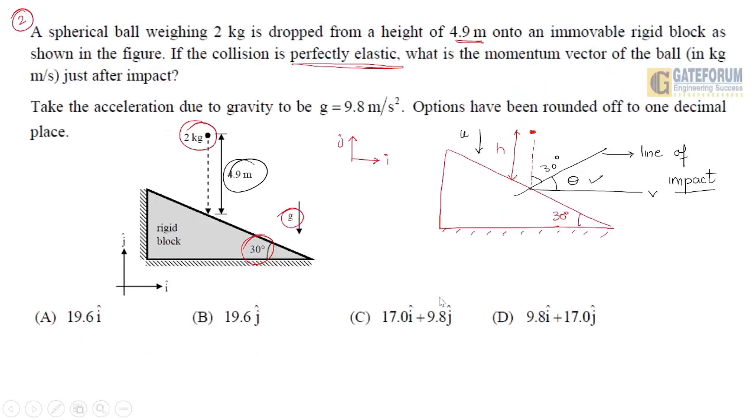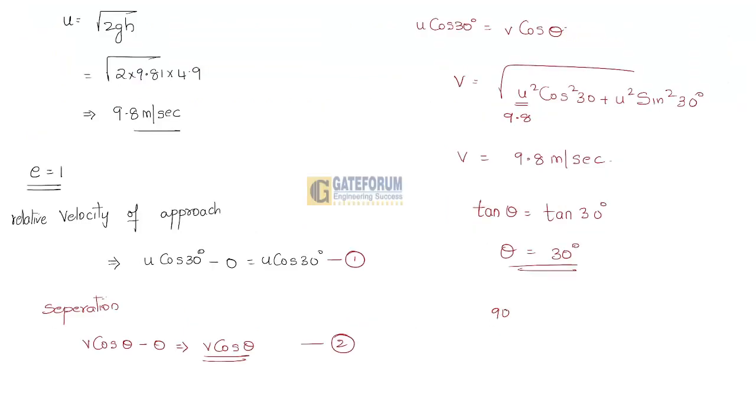So what happens when we are talking about the inclination conditions? Here theta is 30 degrees, which you got. So obviously the remaining angle from here to here will be 60 degrees, right? So the inclination of the plane of section, we call it 90 degrees minus 30 degrees, which will be 60 degrees.